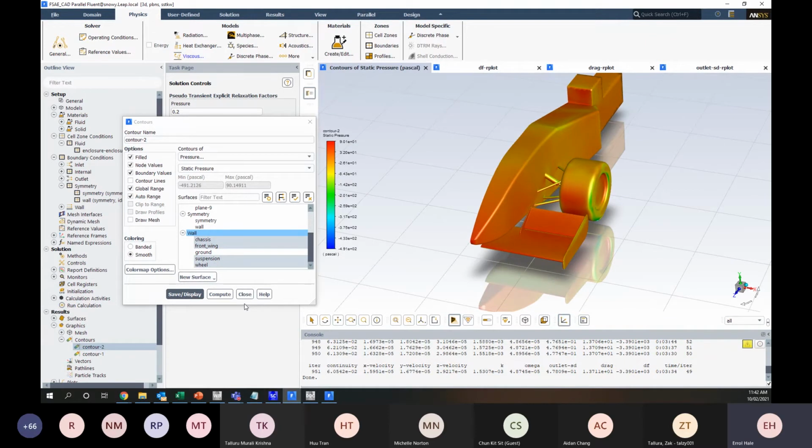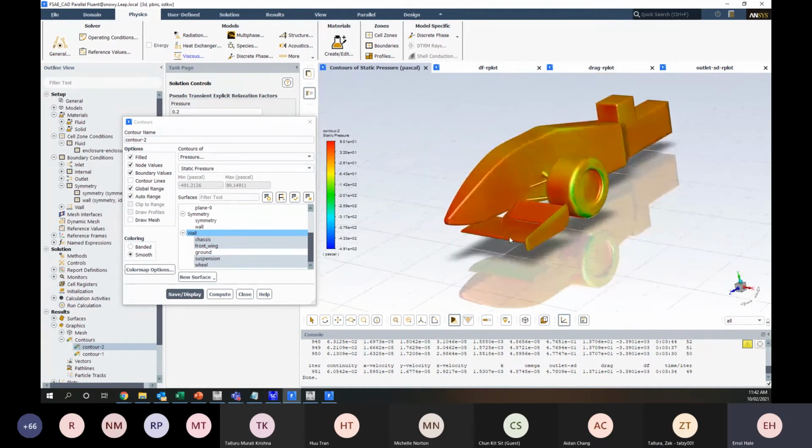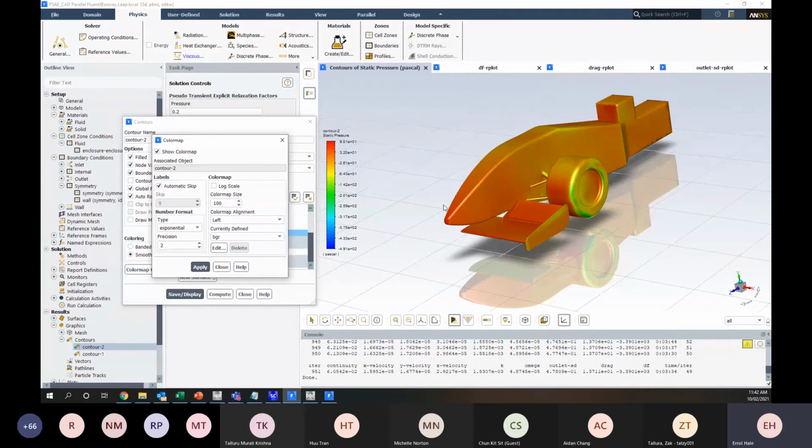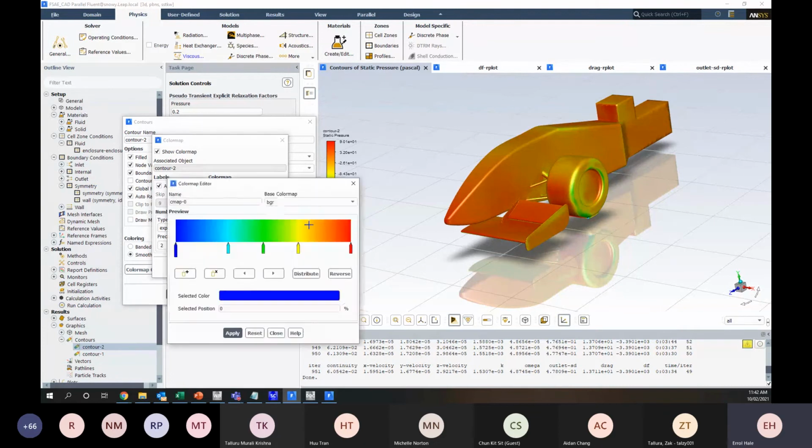One thing I like to do with the pressure contour when assessing external aerodynamics of a vehicle like this is to change the plot to basically put zero pressure in the middle, so you can see more clearly what is actually sucking and what is actually pushing. Because you'll see, if you can see here, that our 0 point's actually up here, and we're getting a lot lower pressures, gauge pressures, static pressures, than we are higher pressures. So one thing we can do is we can edit this, make it split.